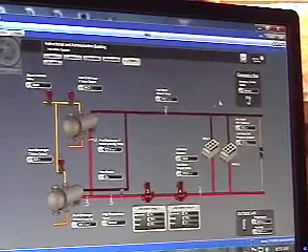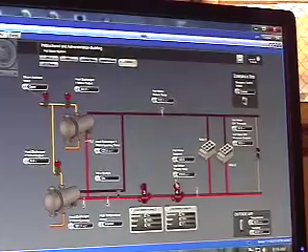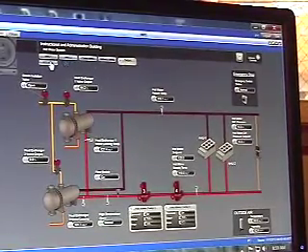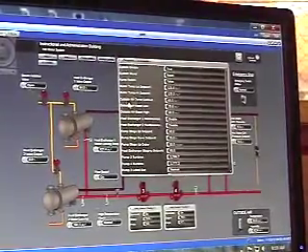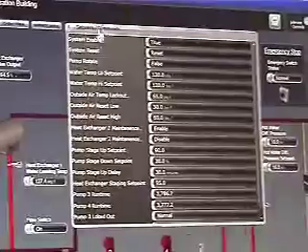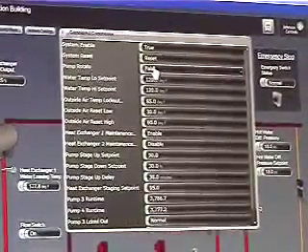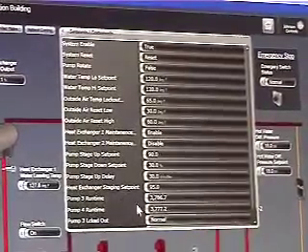Position of emergency stop, and this is just your return, lets you know what kind of load you have out in the building. You have about a 10-degree load across it. Also have a link to your BTU meter as well. Here's your set points. Your pumps automatically rotate, but if you want to rotate the pumps, you can just right click and hit rotate. You can look at your run times of your pumps right here, both about the same.